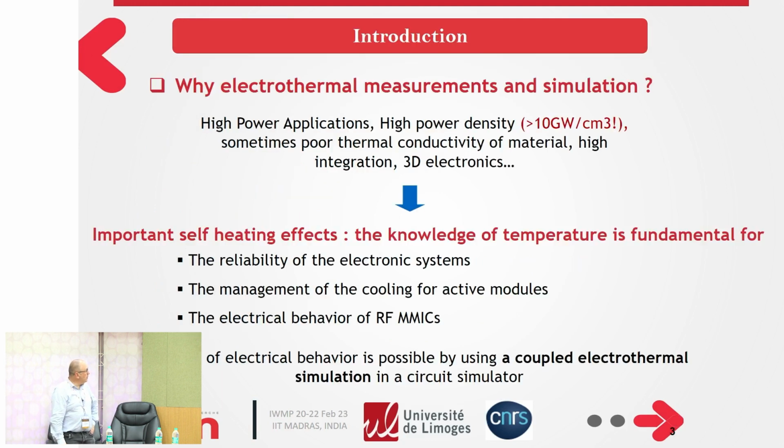So why electrothermal measurement and simulation? Today we have very high power applications with high power density, with the increase of the frequency. Especially, we can have more than 10 gigawatts per cubic centimeter. And sometimes we have poor material thermal conductivity, especially when the device is in package. We need to cope with the temperature and to know exactly what the temperature of the device is for the application. So this self-heating is very important.